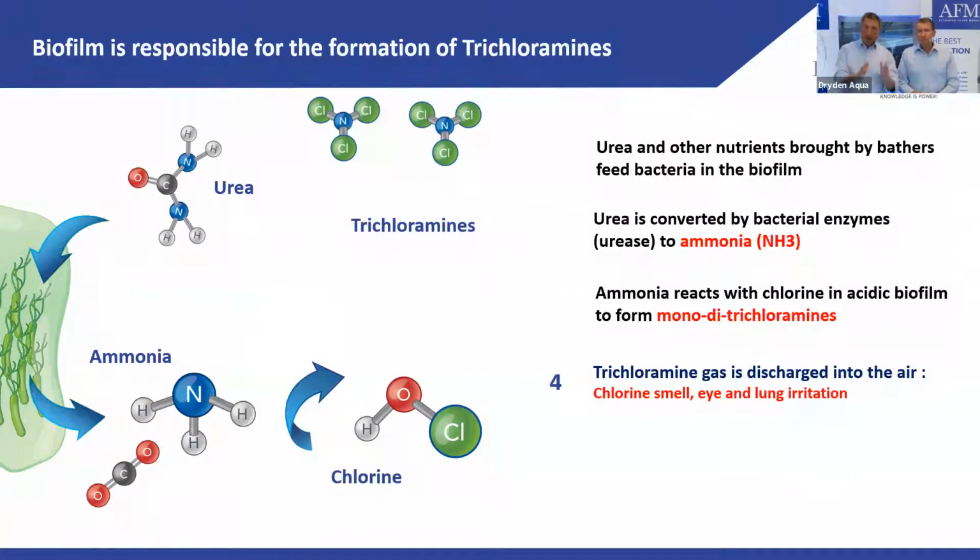Now, if you have a bioresistant filter media, AFM, or also DE, the urea will stay urea. You have 80% urea and 10% ammonia. So the ammonia can react to mono, di, and trichloramine, but only 10%. And the urea will form organochloramine, which we will see later on.